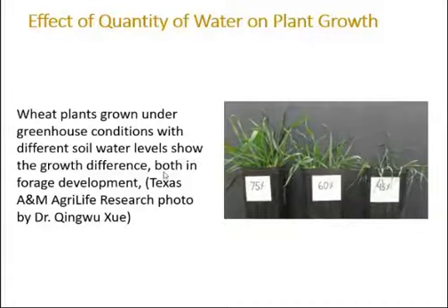If you always keep your plant in a drying condition, you are keeping it very close to the permanent wilting point. That's not good for the plant. They will wilt. If you keep saturating your plant, all the pores are filled with water, and then you have less oxygen and air in the pore spaces of the soil, and that is also not good for the plant. The plant dies. They need oxygen as well.